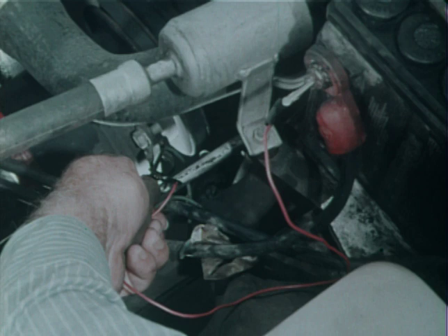An audible click indicates that the clutch is engaging. If the clutch does not engage, the clutch coil is defective and must be replaced. In this case, the clutch engages and the malfunction lies somewhere else.